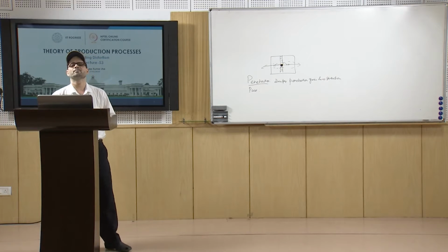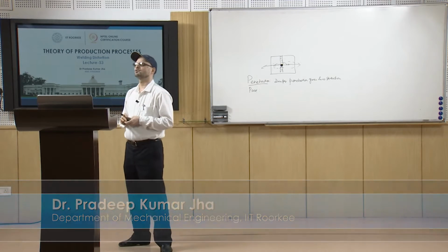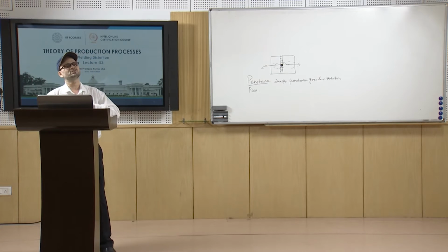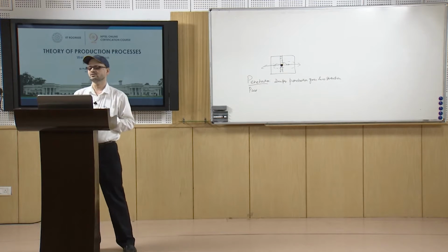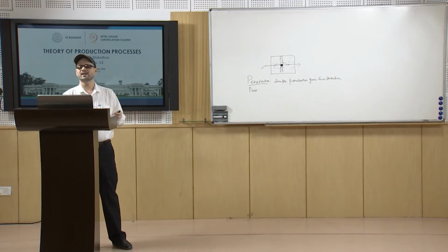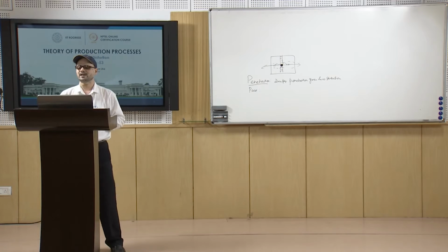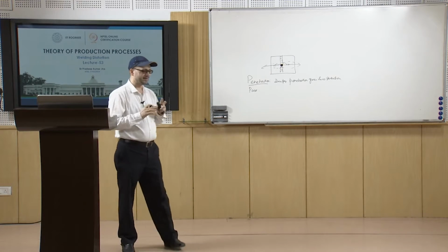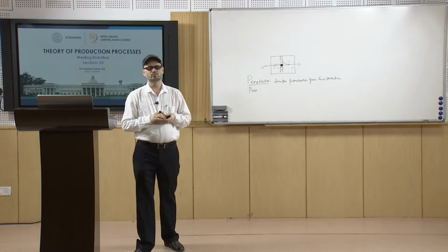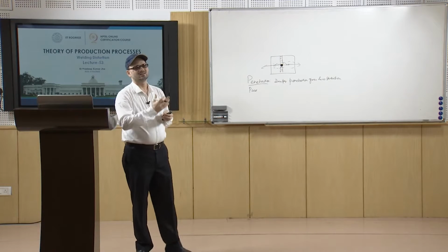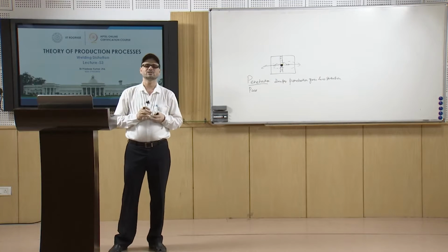Now, talking about the procedures, we talked about the welding processes and parameters, and other procedures. We should try to go for mechanized welding, which will give you less distortion as compared to non-mechanized ones. Single pass, high speed welding should be preferred, which is likely to give you less distortion as compared to joints with multi-pass, low speed welding processes.